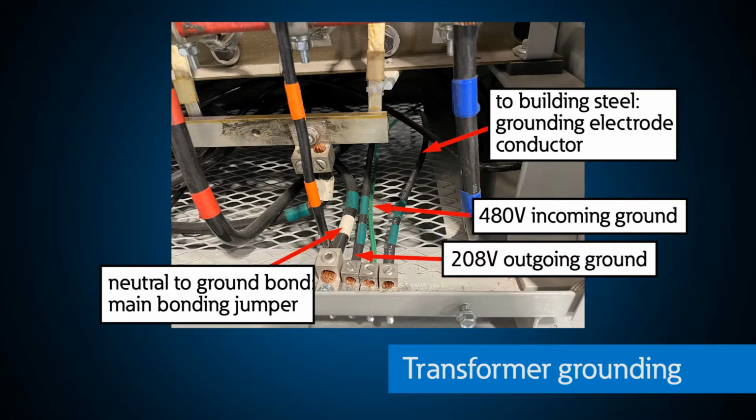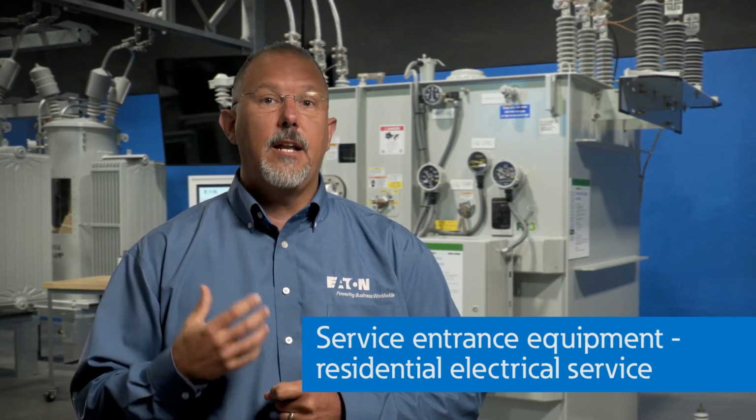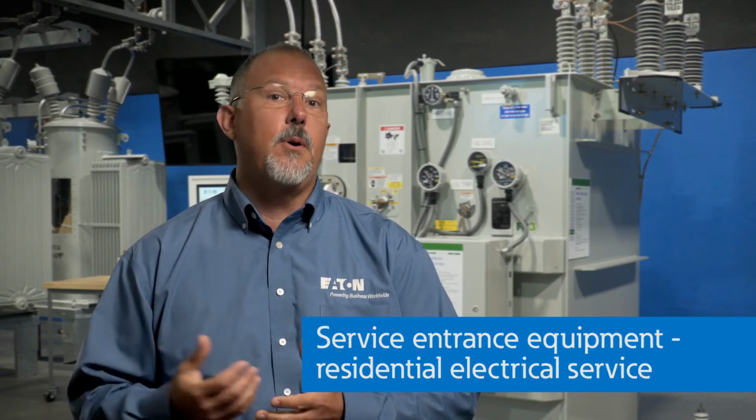Here's an example of a separately derived system with delta-Y three-phase transformers. Here is the grounding electrode conductor, and the main bonding jumper. This establishes the grounded conductor that we talked about in the previous section. Let's show you how a residential service and a load center are typically grounded and bonded.